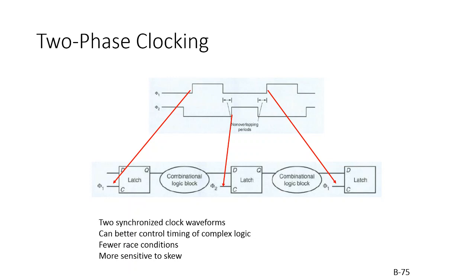we talked about this previously, so I won't spend a lot of time on it, but basically it's supposed to wait on another value, and you didn't build the logic that it waits, and so in one, like a multiplication occurs, or we'll just do a simple A and B occurs, and then it's supposed to be the result of that and C. Well, since you can, let's say with a programmable logic device, have all of these running in parallel, A may be ANDed with B at the same time as C starts to AND with the output of A and B, even though the data hasn't completed its path through the A and B yet.